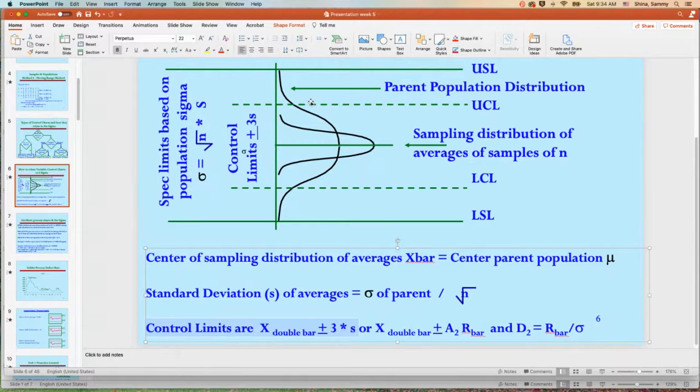We want to make sure absolutely, though, that it might be what they call a false positive, meaning it's a black swan. That's the nature of things, and once in a while you're going to get a point outside the control limit based on the standard normal curve. But if it happens this time, then that means something is wrong and we better investigate it.